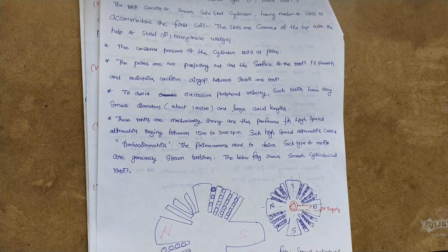Pole pitch, or number of slots per pole, is known as pole pitch. It is the center to center distance between two adjacent poles. We have seen that in one rotation of a conductor, two poles are responsible for 360 degrees. Four poles will be 720 degrees. Similarly, 180 electrical degrees is equivalent to one pole. If you consider two poles, one pole is responsible for 180 degrees. 180 degrees electrical is also called one pole pitch.